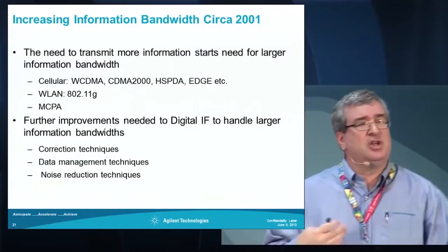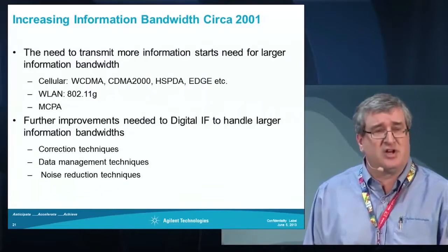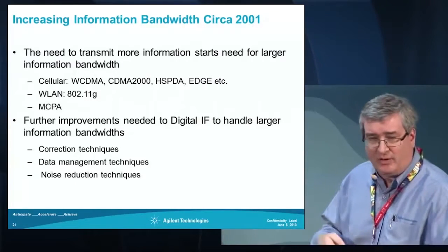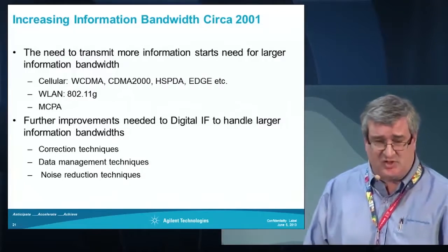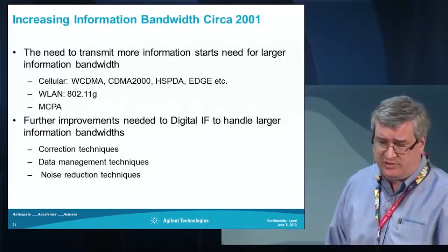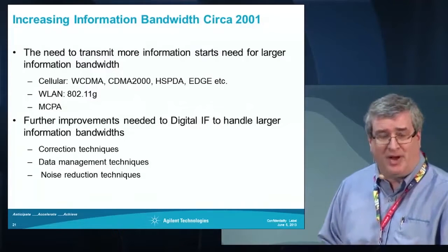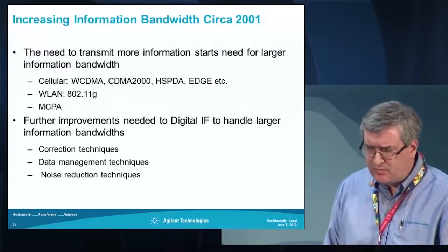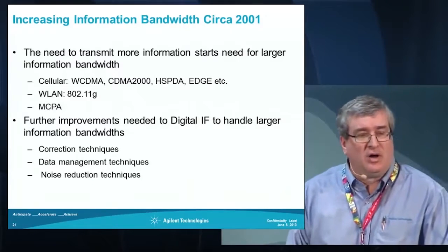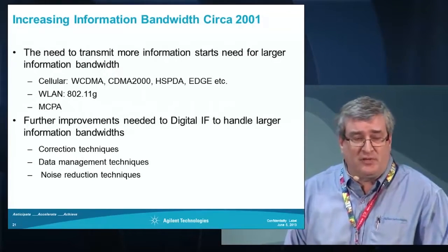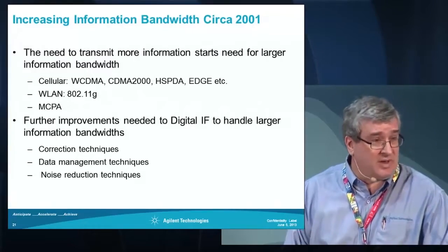There was a change in the way base stations wanted to do their stuff, where they wanted to do a single final carrier, a final PA at their base station, so they wanted really wide bandwidth signals to analyze how their power amplifiers worked. And so for us, what this meant was we needed to increase our IF bandwidth. For the PSA, when it first shipped, for example, had a 10 megahertz IF bandwidth. At this point, we wanted to get about 80 out of it.